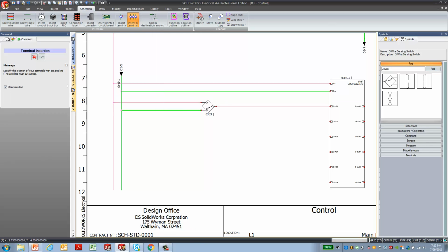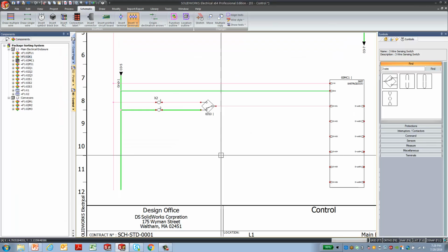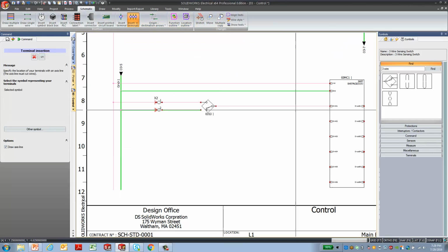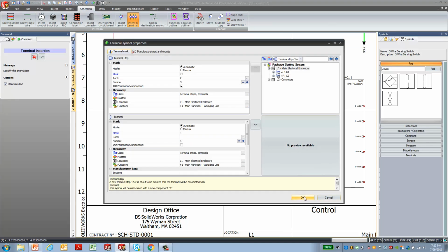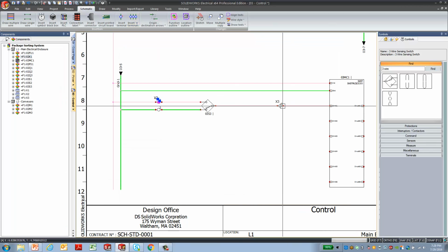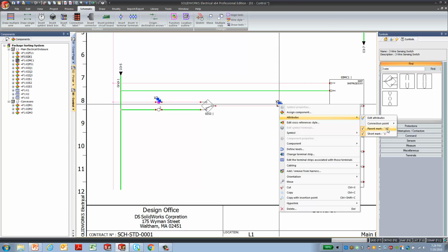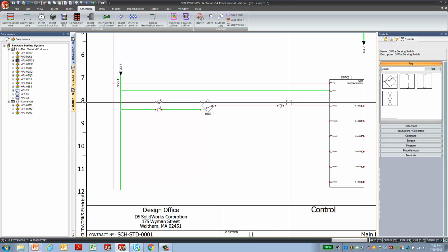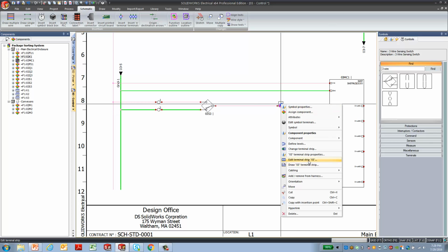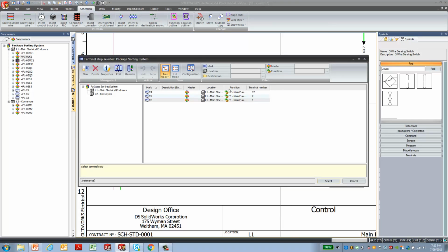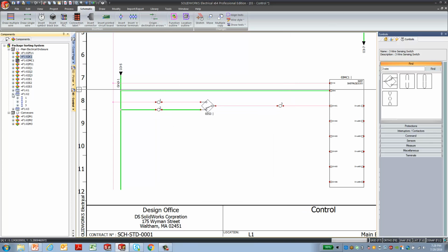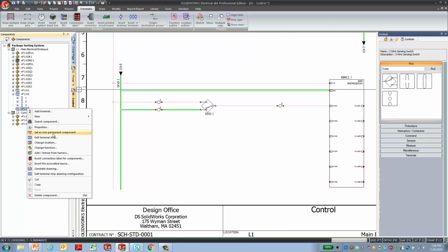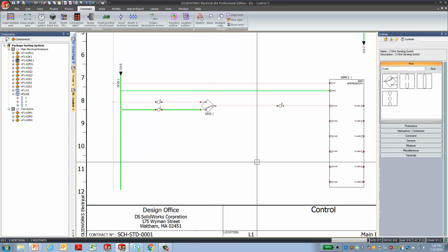The same way I created the terminals for the motor, just drag a terminal, say OK, and we'll add another one, say over here, going out. Okay, that looks good. And I'm just going to hide these for a second. Oh, if you see this says terminal strip 1, 2, and 1, that's because I made a mistake. Change terminal strip. I accidentally created a 3rd terminal strip. I only want a 2nd terminal strip. So now we have terminals 1, 2, and 3 of X2, as you can see. And terminal strip X3 is empty, so we'll just go ahead and delete it from our system.